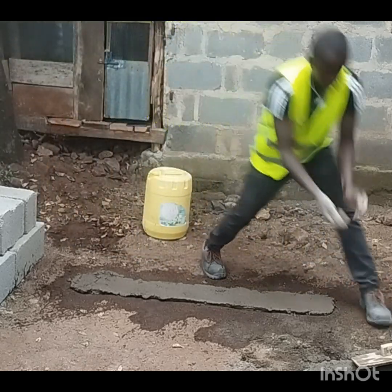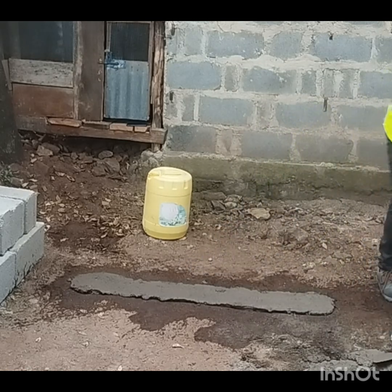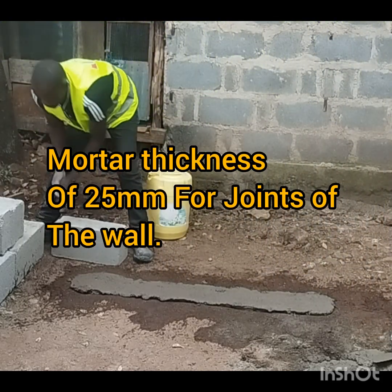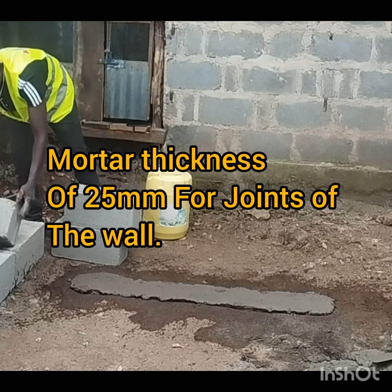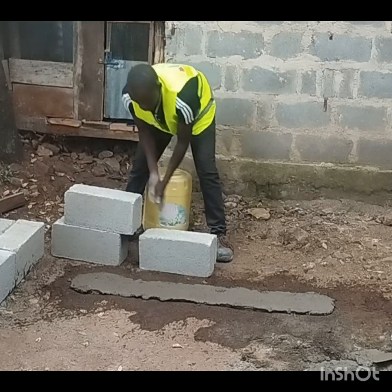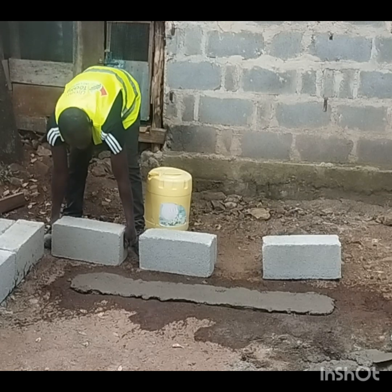So we are going to use 25 millimeters. Sorry, that is 1 inch. Once you've gotten your strong mortar, once you've used the ratio of 1 to 3, either by batching or by volume, even if you do the 1 inch, you'll still have a strong bond between the stones. It is very important for us to know that 1 inch is just good enough.